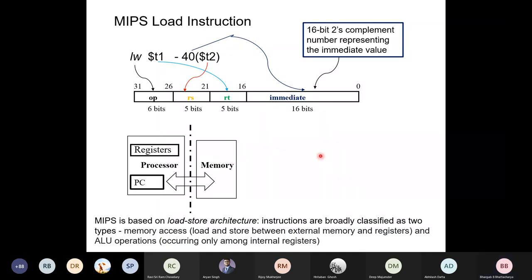You got the point? That's why it is called load store architecture, meaning that all memory access for data is separated. Okay, do you get the point? I cannot write in MIPS assembly language an instruction like add A, B, C, where you access the content of memory location B, access the content of memory location C, then add those two contents and save the value in A. Addition and memory access cannot be done simultaneously in MIPS architecture.